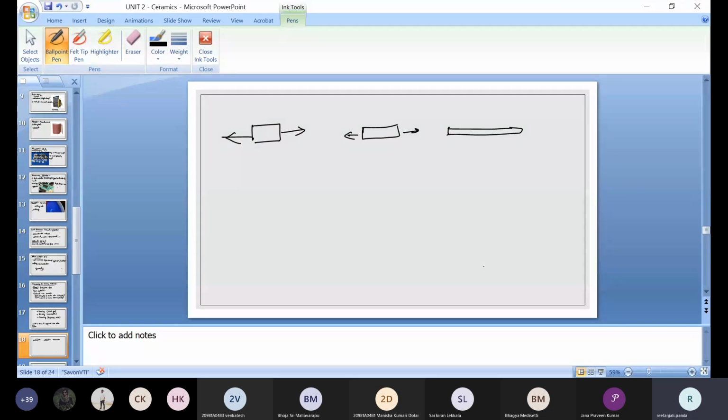And in this case, in the glass drawing process, we will be getting long objects like tubes, rods, fibers, like that. Okay, so there are three processes for glass making. I told you, one is pressing. In pressing, we are heating soda ash, limestone, and quartz material at a time in powder form. We will melt it, then we will be getting molten glass, and we are going to give shape to this molten glass. Okay, that is what your glass making processes are.